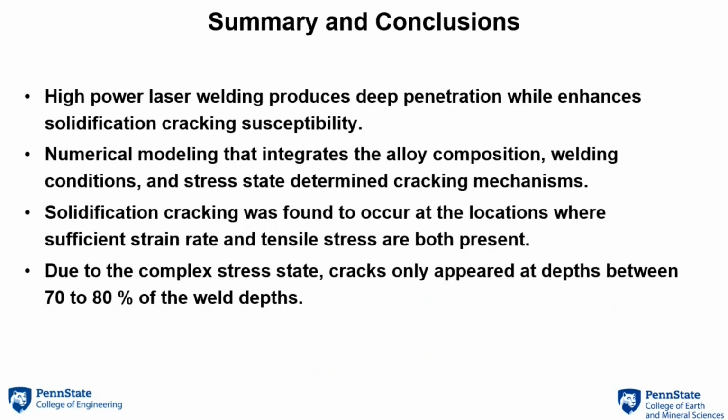Lastly, I want to provide a summary and a few conclusions on this work. High-power laser welding can help us improve welding productivity through deep penetration, while also enhancing solidification cracking susceptibility. To understand these solidification cracking behaviors, in this work, a new methodology has been developed which is able to integrate different components of the cracking issue, such as the alloy composition, welding conditions, and the stress state